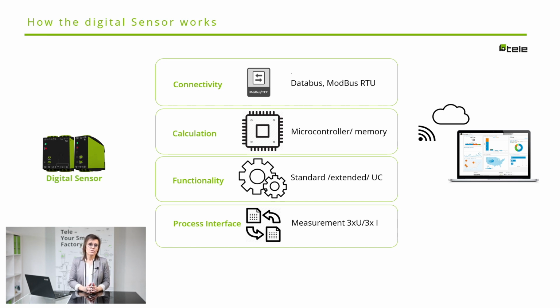The digital sensor supplies values to an intelligent IIoT system that can be digitally analyzed and converted into valuable plant information data. These digital values can only be generated directly from real-time values in a local device or edge device, and it will not be possible to calculate the values in a remote cloud system. The reason for this is the real-time phase shift between the 6 process values. They cannot be calculated by a cloud-based algorithm due to the latency and update rate of such a remote system.